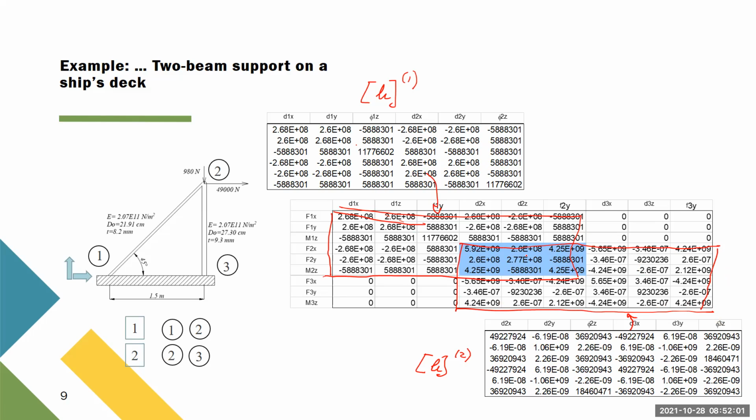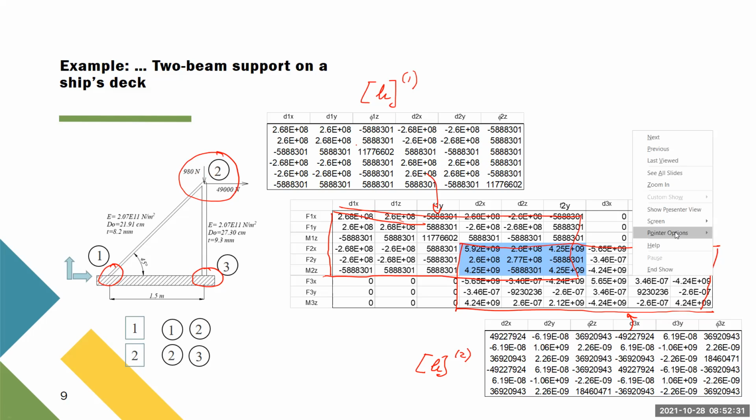Of course, in this part, in blue, you have the combination. Now, not only that, but you see that this joint here and this joint here are completely clamped. So they cannot move, they cannot rotate. So we are going to be left only with 3 displacements, 2 linear, 1 rotation, to calculate in order to solve this problem, okay? So that's something that we have seen many times.